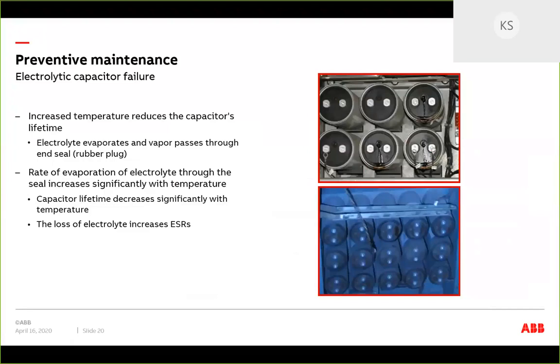We don't want you to get to this spot. Wouldn't that be right, Matt? These are real pictures that I think you or your team have taken. Isn't that correct? Yeah, this is something from the factory. This is commonly what would happen to the DC bus capacitors over time. It could be there was an overvoltage incident, or most likely that the can is rupturing there.